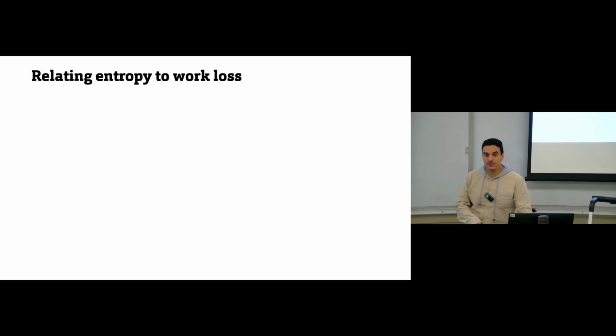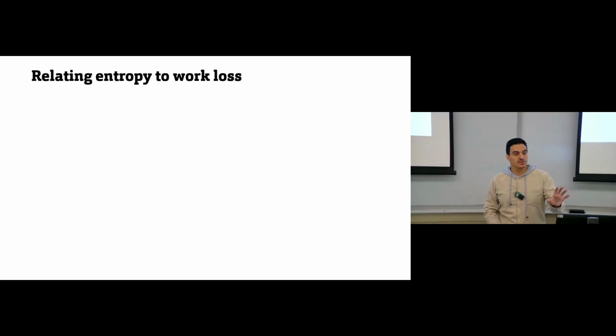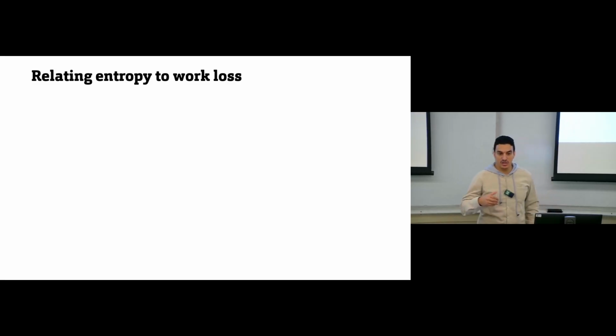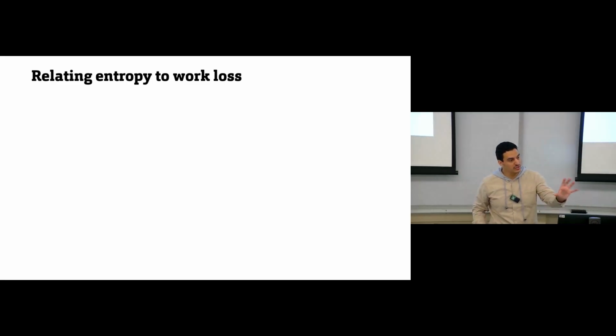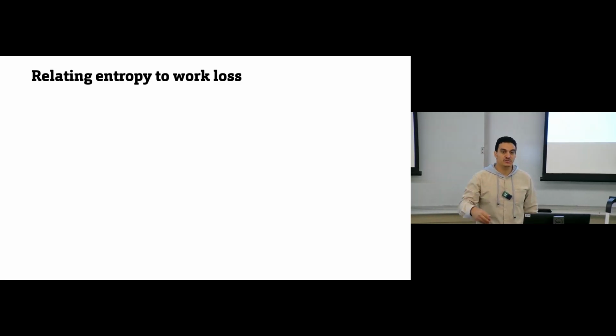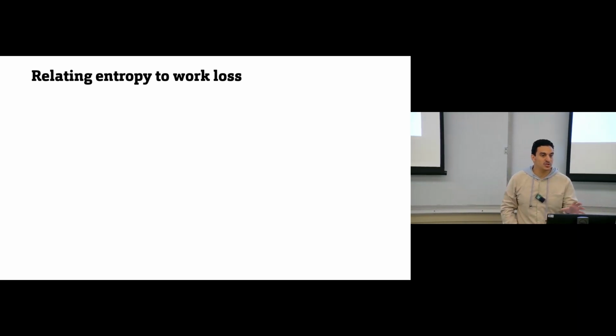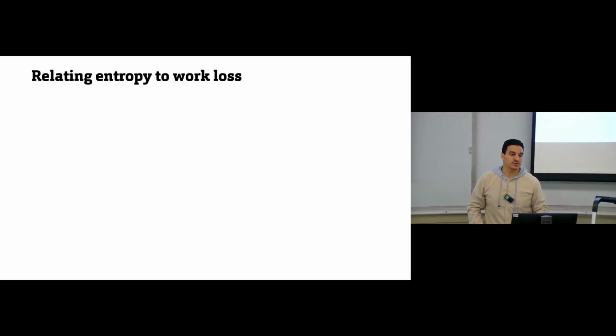So far, entropy starts with the definition of a state property that can be calculated with Q divided by temperature for reversible processes. Then we said we can use entropy to know whether a process is spontaneous or not by calculating the total entropy change. We calculate the entropy change for the system and for the surrounding, and sum both to get the total entropy change. If the total entropy change is more than 0, the process is spontaneous. It will occur without any external force. If the total entropy change is 0, the process is reversible.